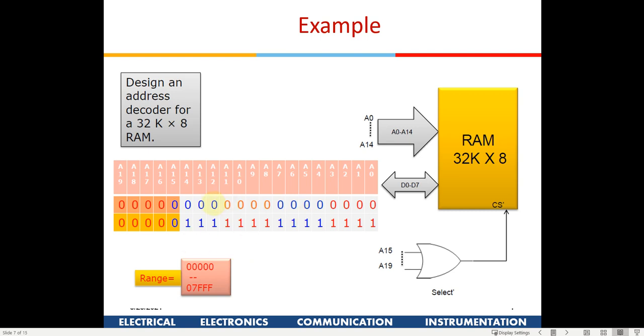Since we have put hardware like this, in the software we have to restrict using this range of memories. When you write a program, we have to restrict ourselves and know what these bits are. Since it has been hardwired like this, we have to be careful when writing our program. We have to restrict our range within this. If you write something else out here in your software, it will go nowhere because there is no chip connected there.